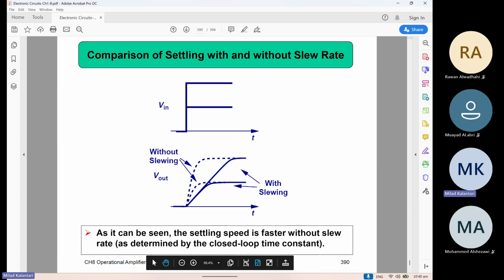So here we are trying to show how it should be if there were no slew rate problem. It shows that it should come up like an exponential like this. If you assume the limit is only the pole, it should be like this or this. They are coming up with an exponential. But in the real case, there is some limit. This slope limit actually changes the shape further.